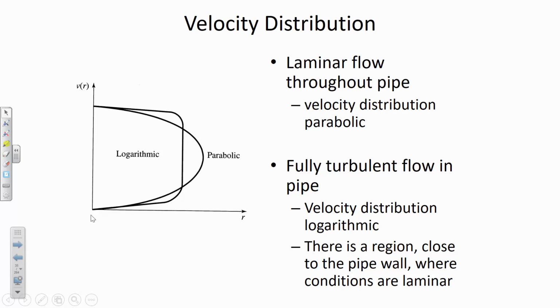And so what we're looking at is this would be the bottom of the pipe, where there's zero velocity because the water that's immediately in contact with the pipe, remember, is experiencing the no-slip condition, where it can't move at some positive velocity over a surface that's causing resistance. Instead, the water velocity is 0 at the pipe, and then the further away you get from the edge of the pipe, the velocity is increasing.